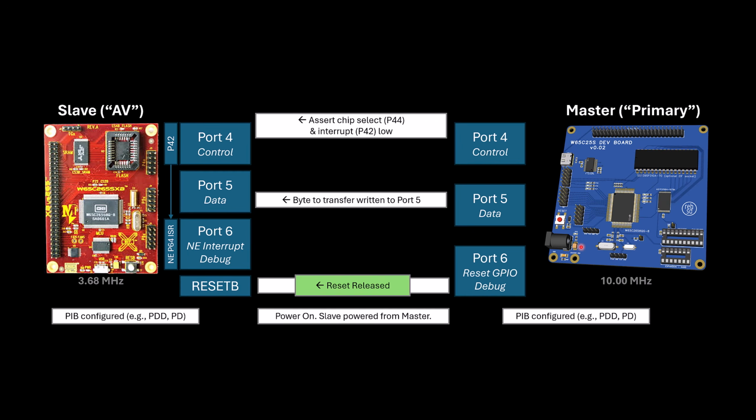Being that that's the case, I need to somewhere get this signal to a different spot, whether I use IRQB or have something a little bit more dedicated to PIB, which I'm just going to use pin 64, which is a negative edge interruptible pin.